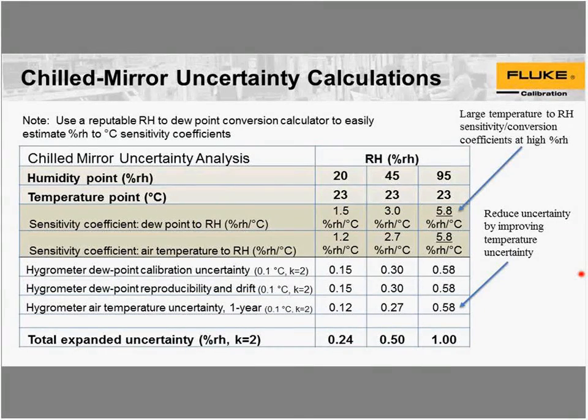I would say that the two-pressure generators on the market also require temperature calibration. So I think we have to calibrate 5 or 6 temperature sensors on it, and also calibrate 2 pressure transducers.